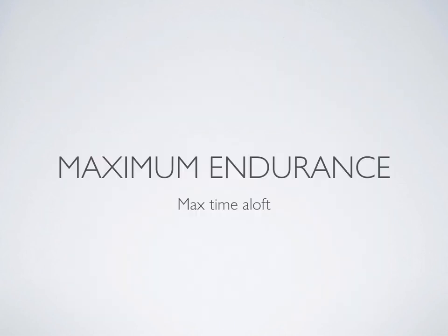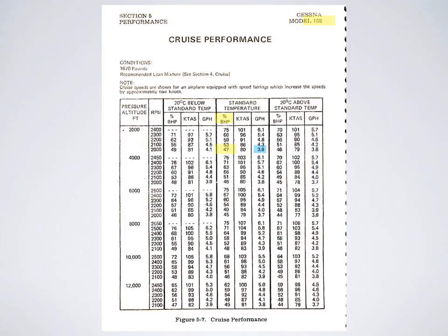Now we're going to look at maximum endurance. So remember from the pilot operating handbook performance charts, we had 45% power as our best endurance power setting. But we know that as we reduce power, we can also reduce our fuel burn. And since our goal is to stay in the air for as long as possible, not in the previous case, which was to fly as far as possible, my question is, can we reduce our power and our fuel burn any lower than 45% and remain airborne?